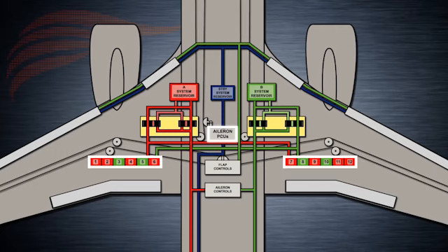Each hydraulic system powers a specific set of flight spoilers in such a way that there's no asymmetrical deployment when there is a hydraulic system failure. One-sided deployment of spoilers is also avoided with this redundancy.